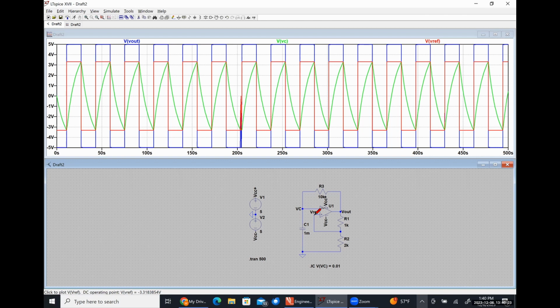This is what's known as a single stage. It can only really drive capacitive loads. Its output resistance isn't high enough to connect a resistive load and not lose the gain.